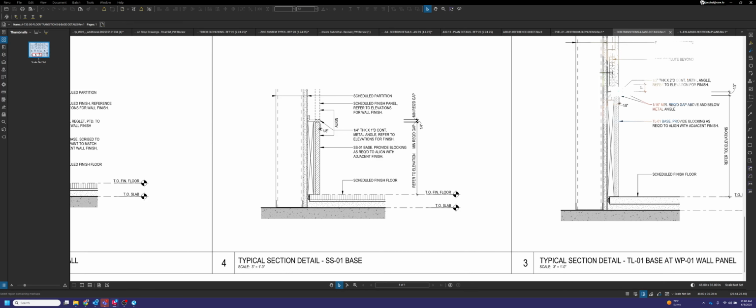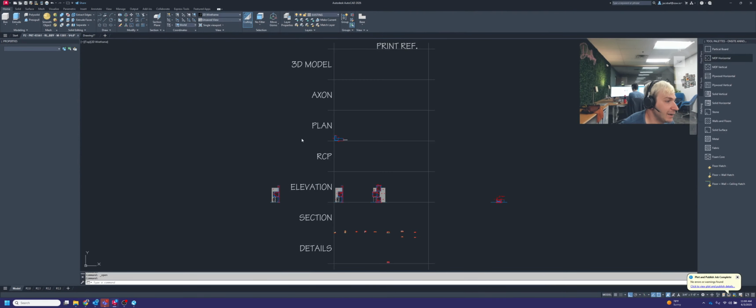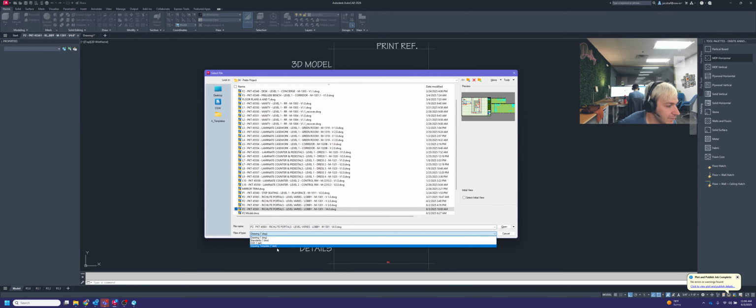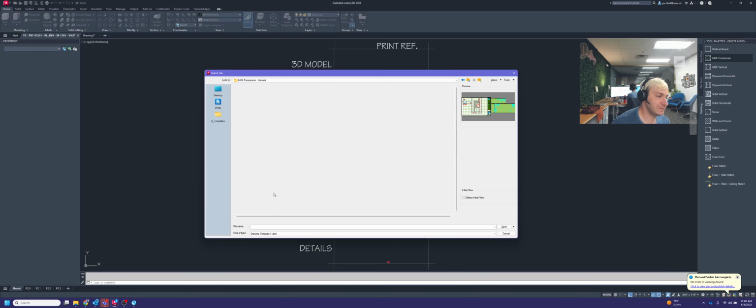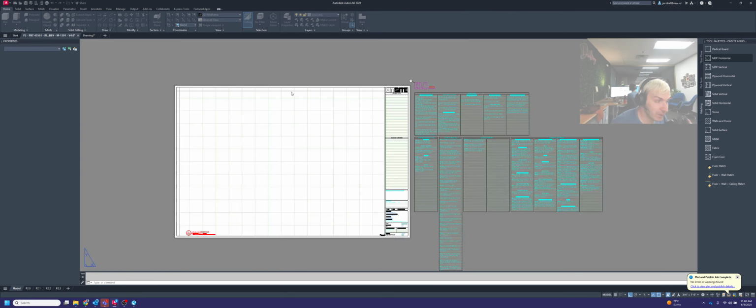I'm going to go into AutoCAD next, and I'm going to open up a file. I got something pulled up already, but we should be looking for the drafting template for Proscenium. So you're going to navigate to your OSW drive, go down to 6434 Proscenium, go into Drawings, Prelim Project, and you should see that drafting template there is a .dwt file. We're going to open that up.